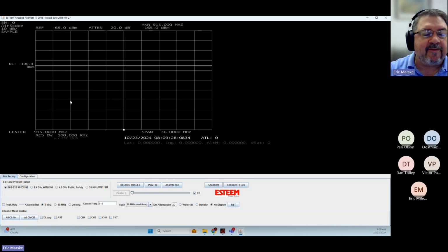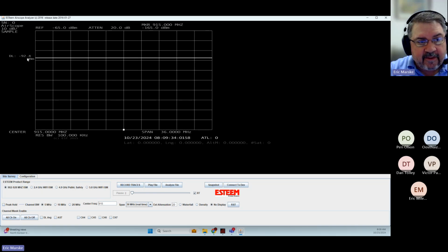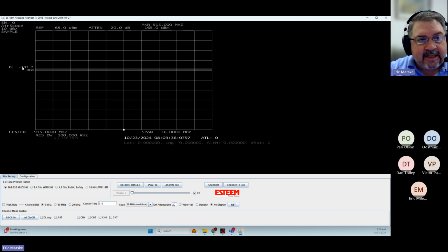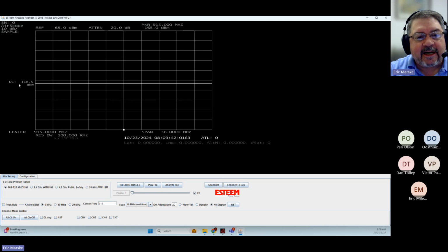We've also put in a couple different markers in here that will help you. You can actually move this display line. As I mentioned before, if I move it up here, you'll see there's the minus 75. We'll see where that actually applies here. We also have a marker that works on the frequency side. As you notice here, our center frequency line is 950 megahertz, and the entire span covers 36 megahertz wide. That means each one of these blocks is 3.6 megahertz.